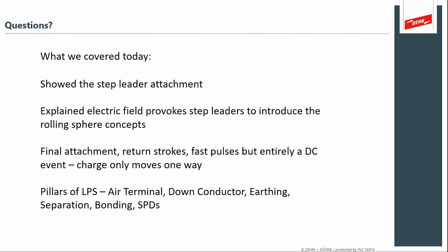And so all of the down conductor materials and the connectors are all tested and rated and have been surge lightning tested to validate that it meets that LPL level. So you're designing a system for the smallest lightning stroke, and you're placing the air terminal spacing to capture a small stroke, but you're also applying materials that can withstand the high end of the stroke.